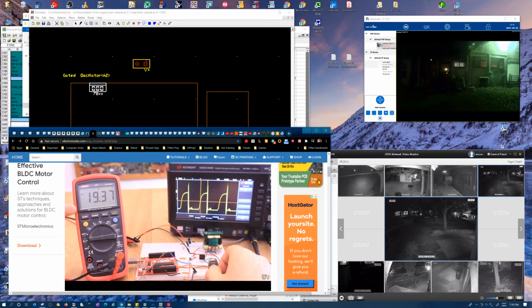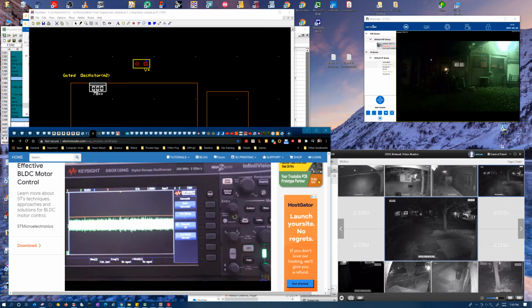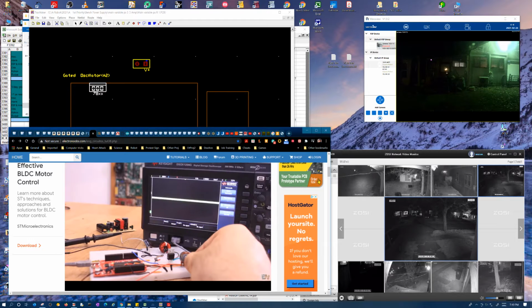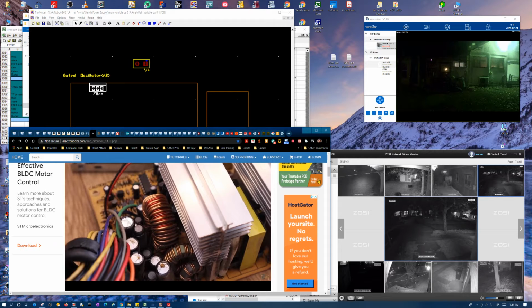A disadvantage of this converter is the output noise. Since we have a discontinuous current at the input and the output, that will create a ripple, and the output voltage will have noise. But that is common with all switch voltage converters, and we could just ignore that for everyday circuits. For more precise voltage values, you might want to look into other forms of regulating than switch supplies.